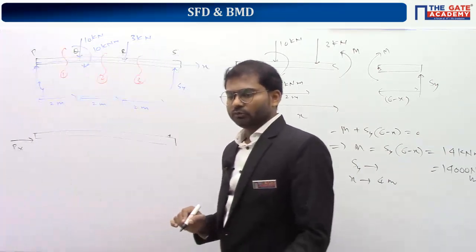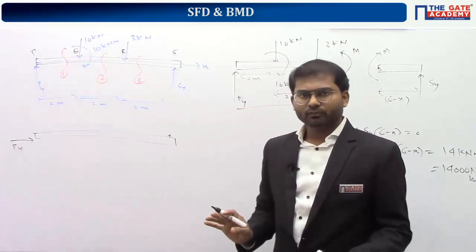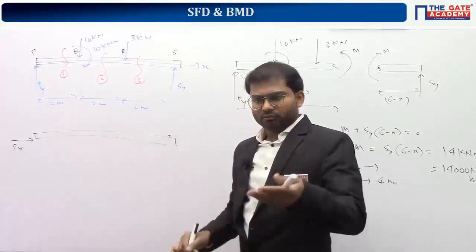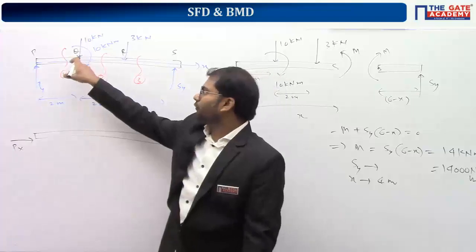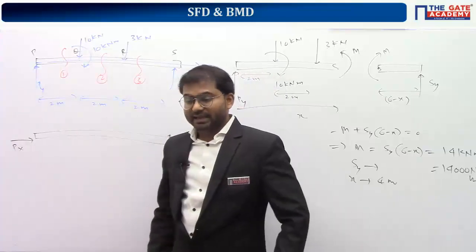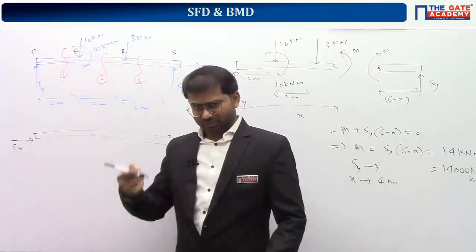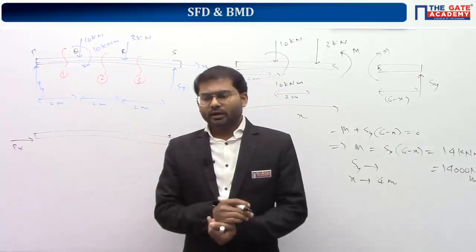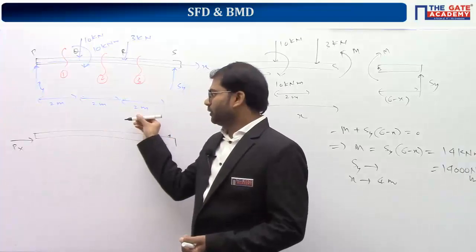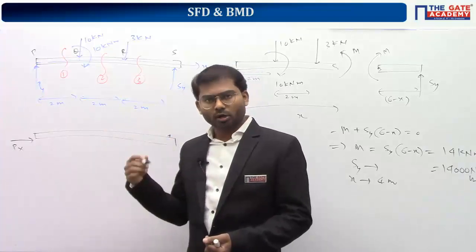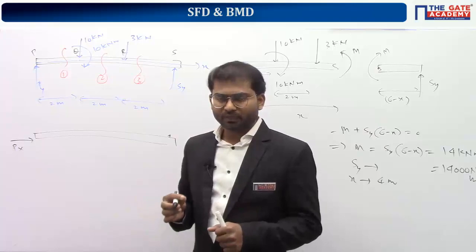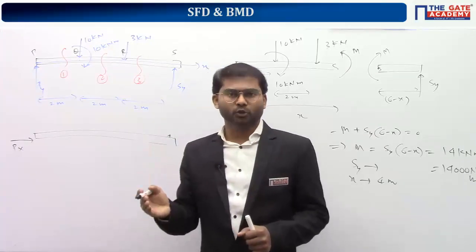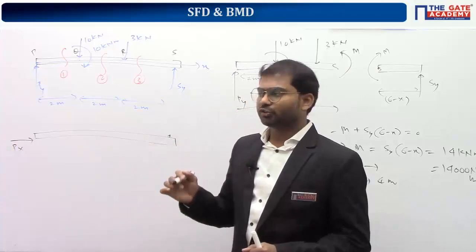At junction Q, there is no normal force, I mean, longitudinal force in other words, because the 10 kilonewton will be giving rise to a downward force and a clockwise moment only. At junction R, 6 kilonewton is acting in an inclined direction, so it will have a normal or longitudinal component. It is nothing but 6 cos 30, which is 6 sin 60, that is 6 root 3 by 2.